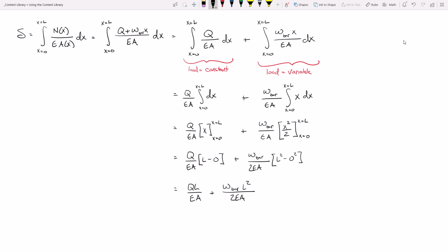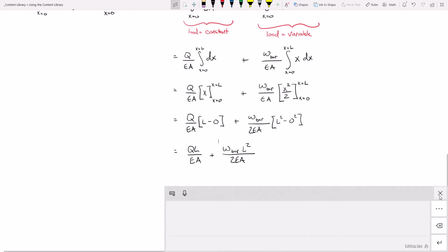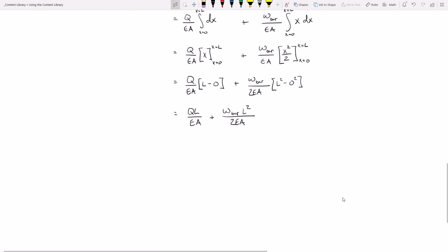Okay, all right. So now we can start plugging and chugging. So, why does this thing keep popping up? All right, so, therefore, delta equals, let's look at this first fraction. So this first fraction, 12 million psi, the area is 0.196 square inches, and then Q is 3886 pounds times the length, which is 600 inches.